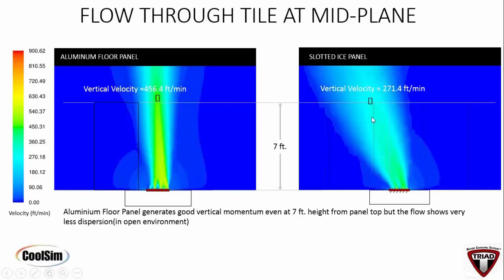It doesn't really matter, to be honest, what direction the velocity is. If the velocity is banging into it at an angle, it's going to intersect that front edge and create the turbulence and swirling that occurs on that front edge, and that's going to provide the fans and the servers with nice cool air. So it doesn't actually jet through the rack, it just comes up and mixes. And you get this mixing that occurs between the cool air on the front of those racks.